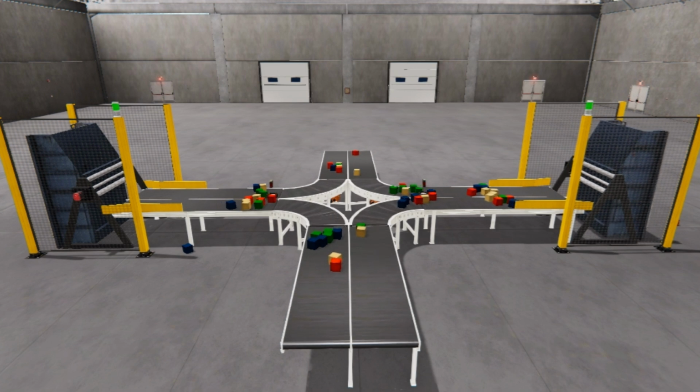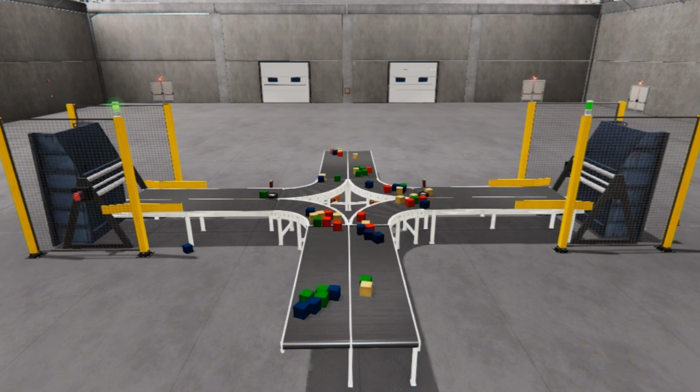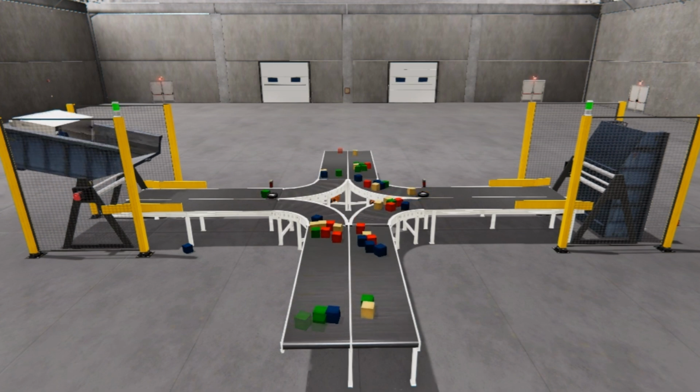This bit will reset when the photocell sees a box or during the first scan of the PLC. The beacon light on each of the box dumpers will flash at 1-second intervals when the hopper is not in the home position or the hopper advance is on.